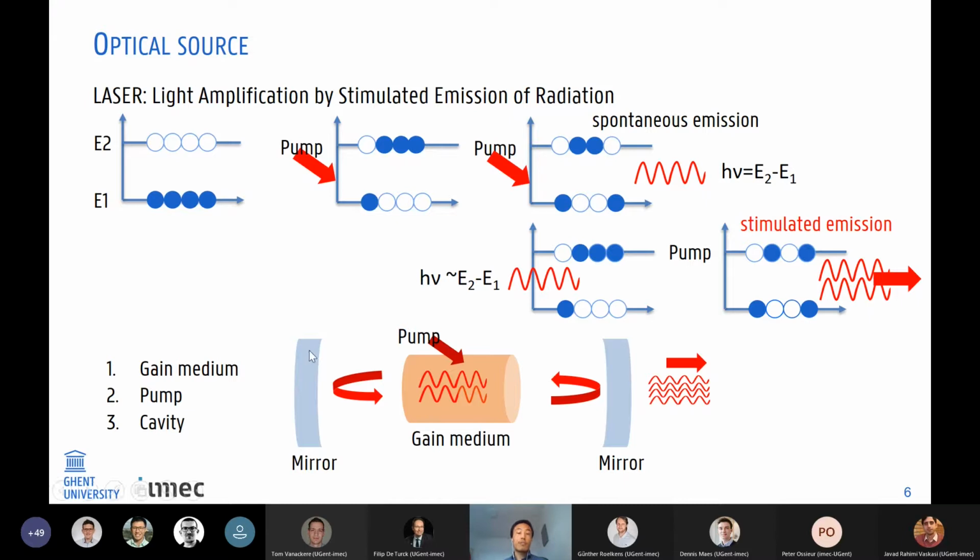For a laser, you still need a cavity. You need a resonator, to let the light resonate inside a cavity. And every round the photon passes by the active medium, it gains some more power or generates more photons. And after many times traveling through this active region, you get more photons. Once the gain could balance the loss in the cavity, then you have the laser established.